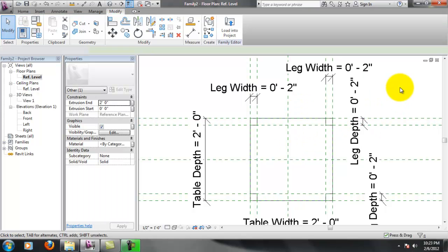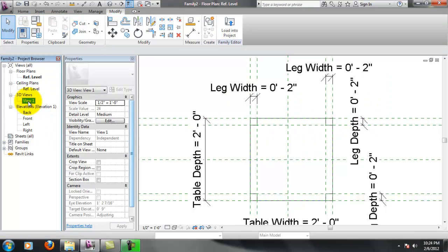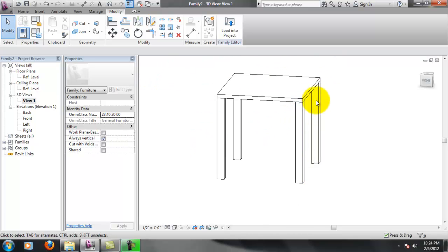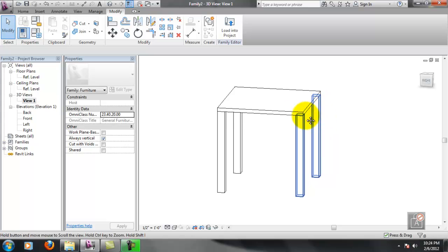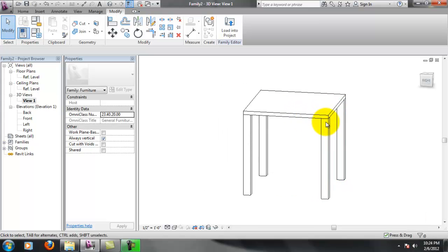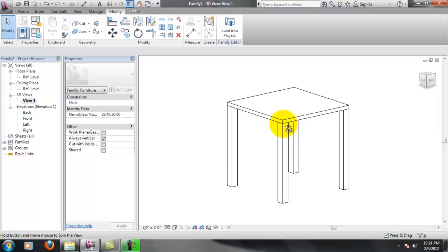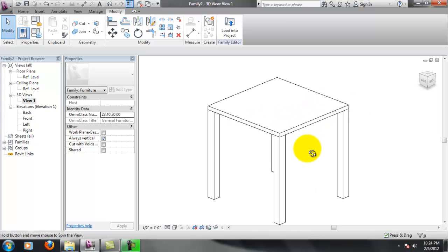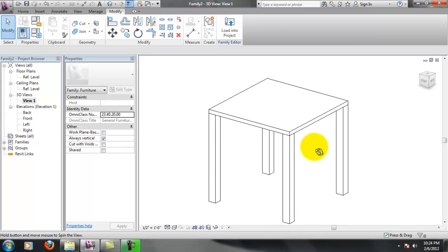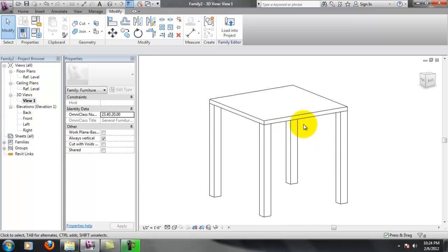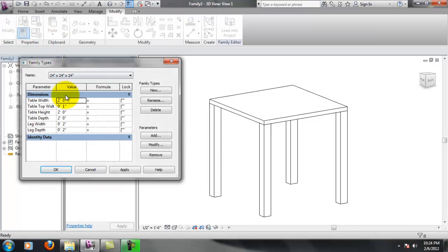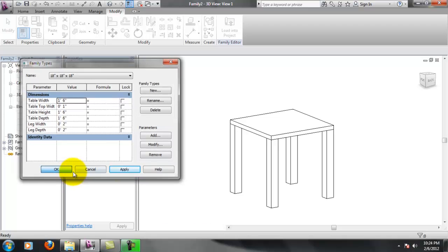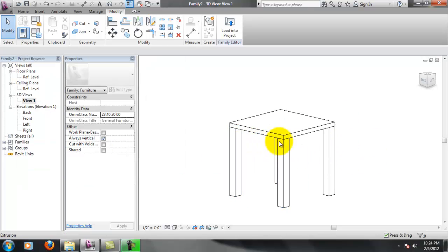That's the first thing. So I'm going to go to a 3D view and see if that corrected at least part of it. So it's good to troubleshoot this stuff in a systematic order, so you're not just running circles around yourself here. If I could remember how to orbit, that would be great. I'm orbiting by holding down Shift and my mouse track wheel, holding it in at the same time. So I'm going to change this back to the other guy. There we go. So you can see the importance of getting stuff to lock it.